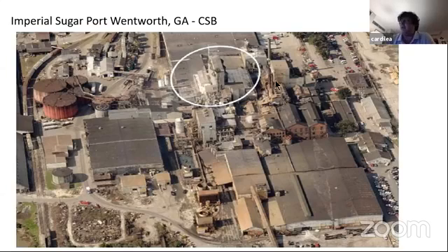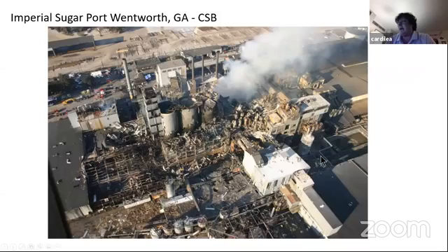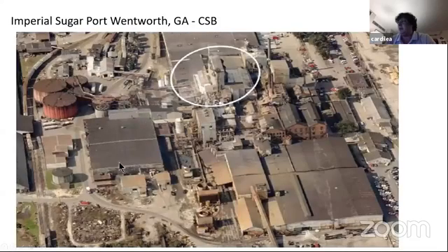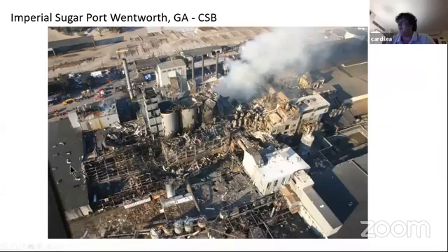So basically, they poorly managed the dust in this location. They caught the dust, they enclosed the dust, it caught an ignition source, and then we ended up with a very, very large explosion because it propagated throughout this whole portion of the plant. Here's the before picture in 2008. Here's the after picture. As you can see, this whole part of the building is there in this picture. It's gone here.